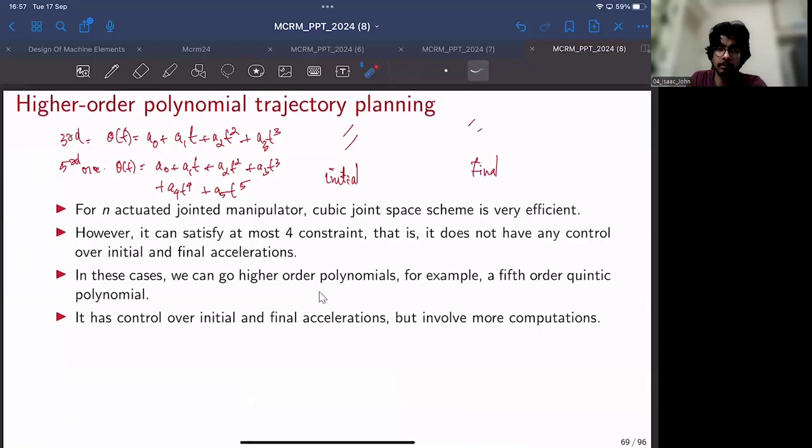But sorry, if you're using an even numbered polynomial, the number of unknowns would be odd. So you have some sort of unsymmetric boundary conditions. You may have 3 boundary conditions here, 1 here, so it may not be symmetric if you're using even numbered polynomial equations. That is why we stick with odd number polynomial degrees.